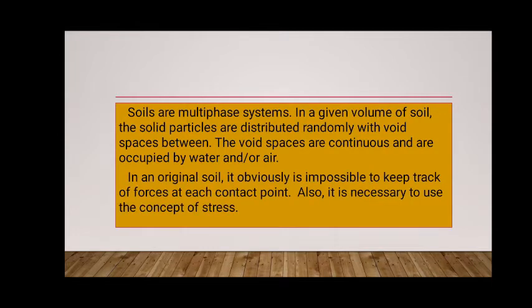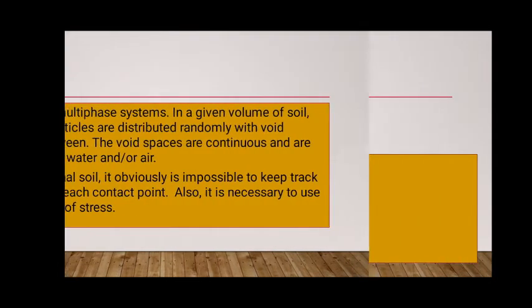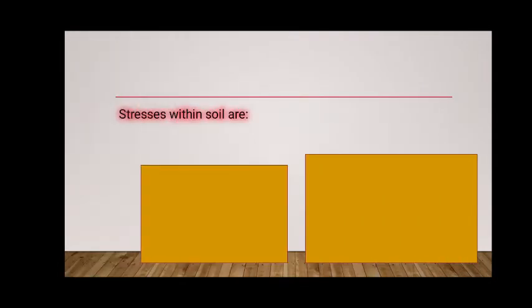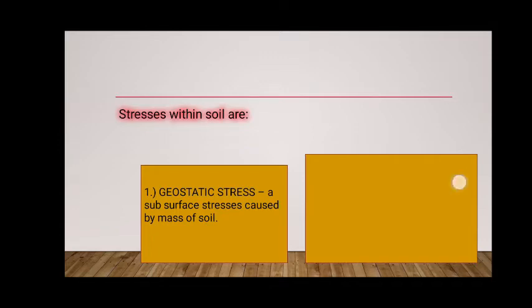In an actual soil, it is impossible to keep track of forces at each contact point. Also, it is necessary to use the concept of stress. The stresses within soil are geostatic stress, which are subsurface stresses caused by the mass of soil, and the stresses due to surface loading.